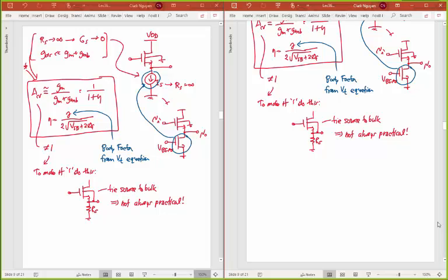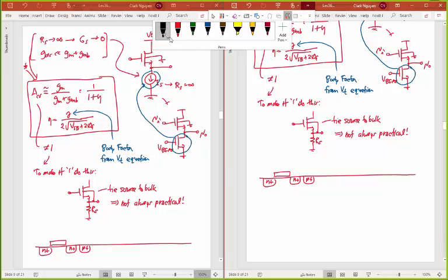And so here's a picture depicting what you would have to do in order to make this work. So say you were doing a CMOS process, and so you know what a CMOS transistor, or an NMOS transistor looks like. You have an N plus junction, another N plus junction, you have a gate right here. And usually what happens in a CMOS process, if you've got NMOS devices, you've got PMOS devices in this as well. And so if you wanted to isolate this device, if you wanted to tie its source to its bulk, so let me go black on these terminals here.